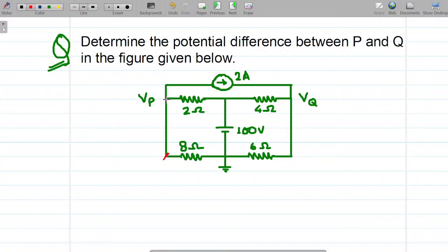Why? Because this is at the same potential. It is short circuited here. So this is VP. So I can also write this to be VP, right? This is the same point. Now, if I travel from this point to this point, this is a current source. Again, there will be a change in potential. Yes, you encounter any element and you see, yes, there will be a change, and so you will find a node here, which is again already defined for you in this question, right? So you don't need to mark it again, right?